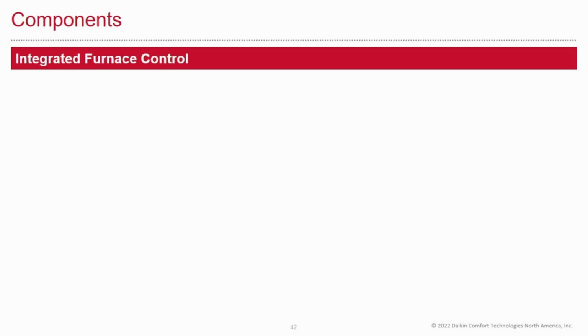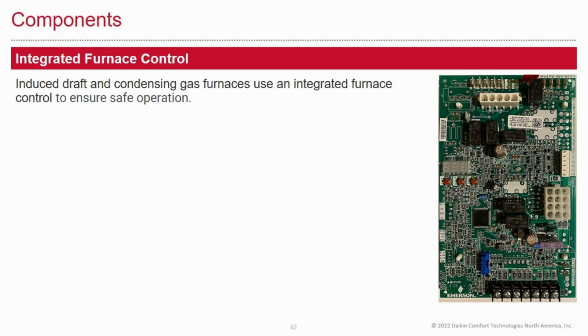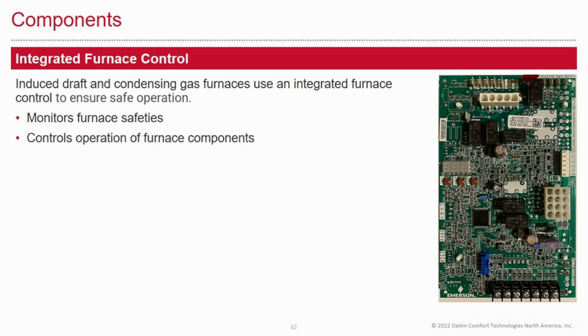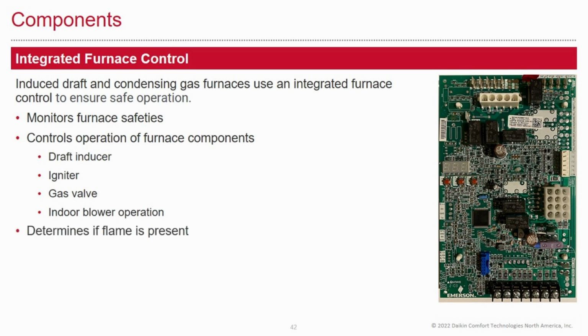Integrated furnace control. Induced draft and condensing furnaces use an integrated furnace control to ensure safe operation. It monitors furnace safeties. It controls operation of the furnace components, such as the draft inducer, the igniter, the gas valve, and the indoor blower operation. It determines if flame is present, and if it detects something wrong, it shuts off the burner.